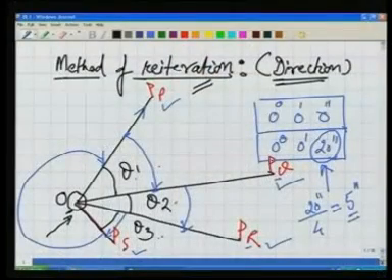Okay, in order to measure the angle, as we have been seeing, we need to bring our tripod and the theodolite and we need to center it. As in this diagram, we wanted to keep our theodolite exactly over the point O. There on the ground, point O is a point, and what we want to ensure is that the vertical axis of the theodolite, about which the theodolite rotates, should pass through the point there on the ground.